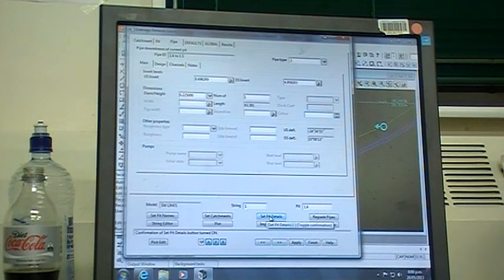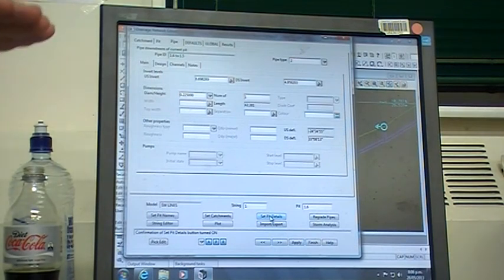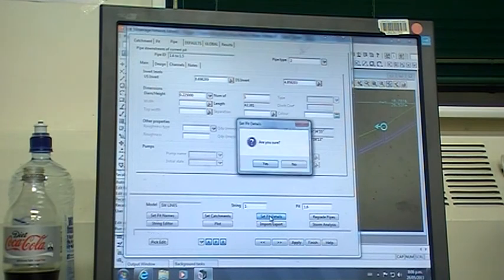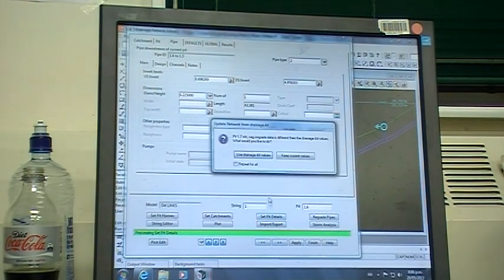Okay, I'm going to set pit details. This will make sure that the pit lids, if I've changed any details on them, it'll update the names, whatever I've done. If I've overwritten the Z values, it'll make sure that they go to whatever I need. But it comes up with this constantly, are you sure? Okay, which drives me nuts.